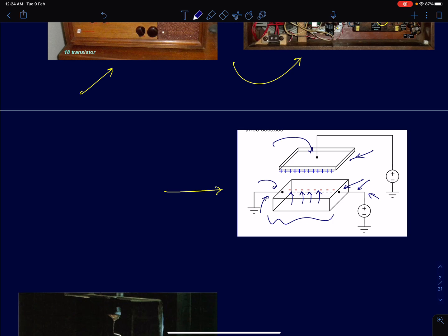So we explained how we attain this amplification operation by the control of a third terminal. What we are essentially doing here is building a dependent current source. Between these two terminals, we are able to generate a current, and that current is not dependent on these two voltages, but rather depends on a voltage at the third terminal. If I can inject the current generated from this dependent current source into a load resistance, and choose an appropriate value of the load resistance and the dependent current, then I can get amplification out of it.